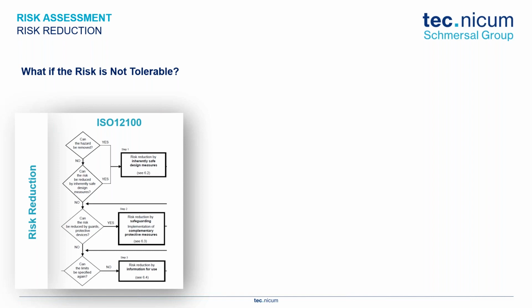And the first thing is, well, can we design this risk out? And then we start thinking about our hierarchy of controls for safety. And can we design these hazards out? Or can we do a substitution on these hazards for something that's a little less dangerous? And for new machines being built, we may have an opportunity for that. For existing machines on the floor, where we're trying to do a risk assessment, it may be more difficult to try to design a hazard out.